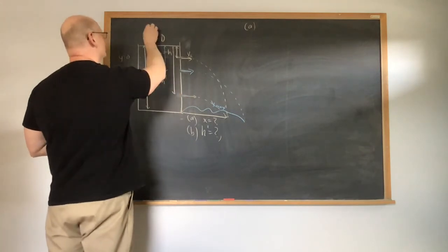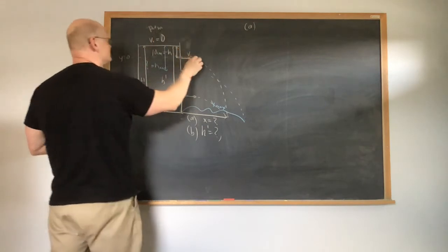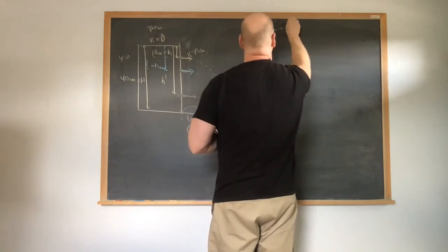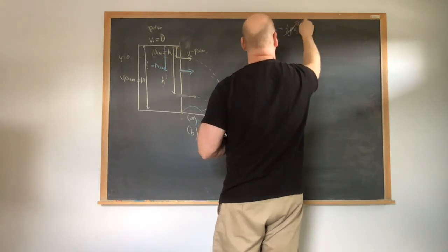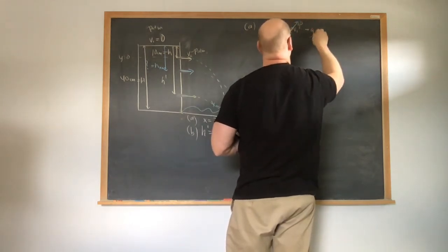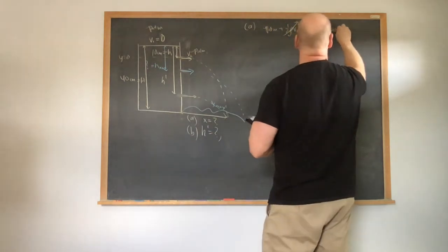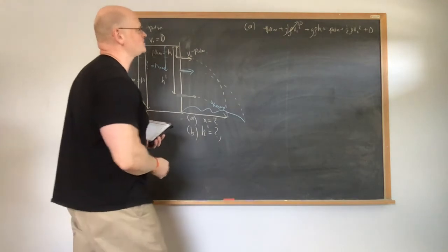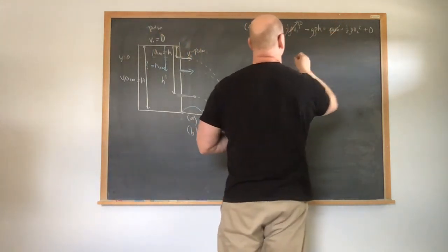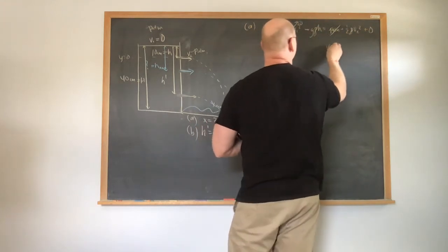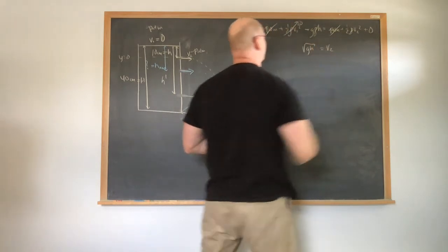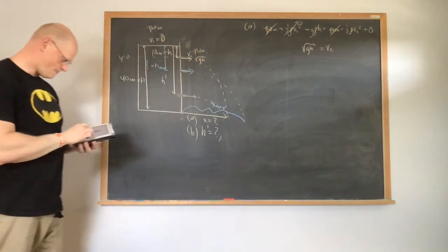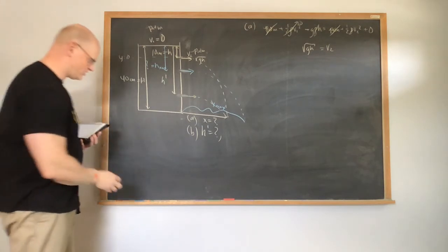And what else do we need here? And again, let's say this is open so that this is at atmospheric pressure. And this is also at atmospheric pressure. So again, Bernoulli's equation says that the atmospheric pressure plus 1/2 times rho times v1 squared, which we already established is equal to 0, plus g times rho times h must then be equal to the atmospheric pressure, plus 1/2 rho times v2 squared plus 0, because again we're calling that our y is equal to 0 location. So again, all this means is that this term has to cancel with this term. So the rhos are going to cancel. So I get that v2 must again be equal to the square root of g times h. So that's v2. So now we know that the water is coming out of here with the square root of g times h. Now, what else do we know? So now we know that it's going to go under parabolic motion from here.